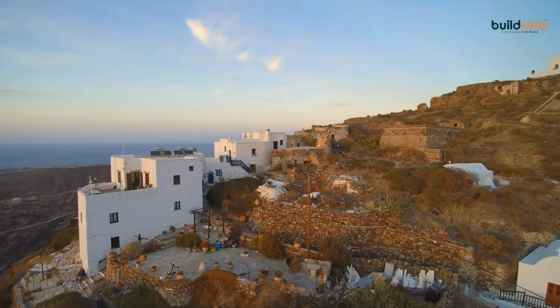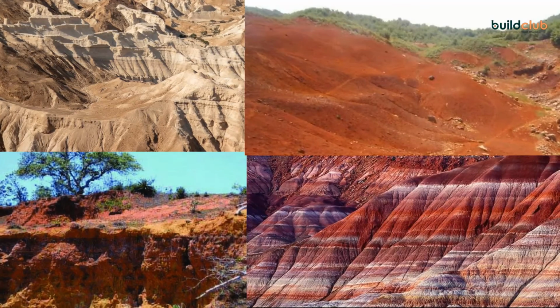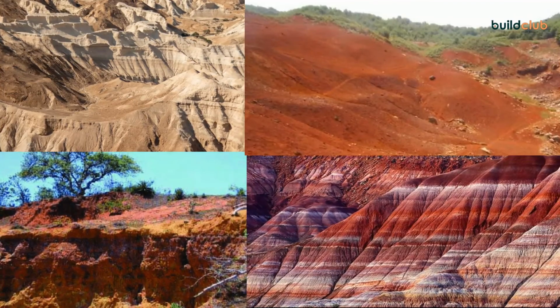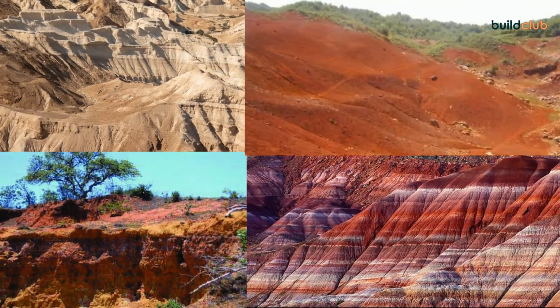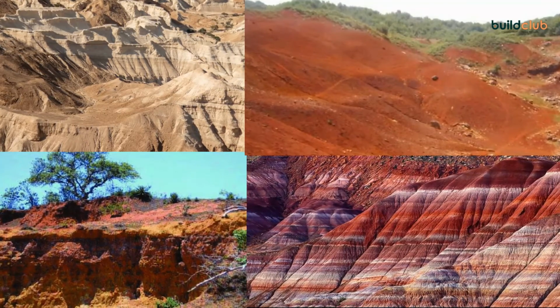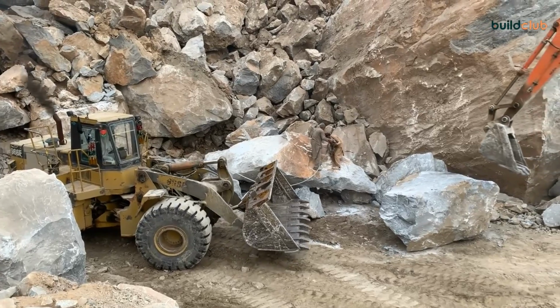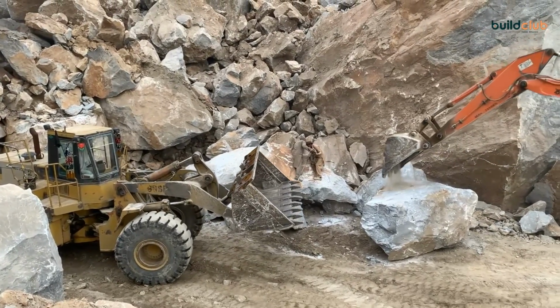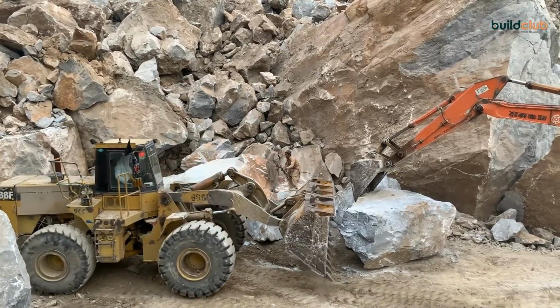As we broadly classify a building construction site, at the top of the list is a hilly terrain site with continuous layers of hard rocky strata. It's densely packed and mostly contains deposits of igneous or sedimentary rocks. Such sites pose huge challenges while executing building foundation works. You need heavy machinery like a jackhammer-mounted excavator to disintegrate big rocks both on and below the existing ground level.